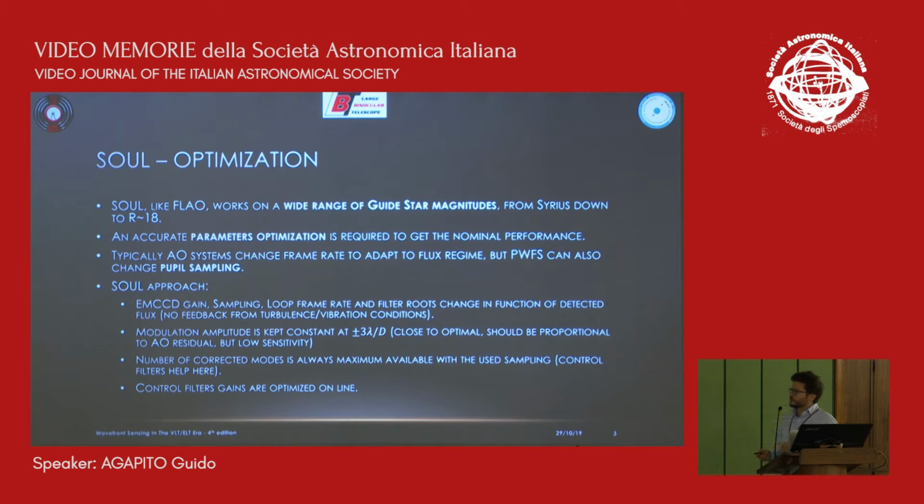Our approach for this system is that several of the parameters, as you can see here, the gain of the MCCD, the sampling of the loop, the filter roots change in function of the detected flux, so in function of the magnitude of the stars.